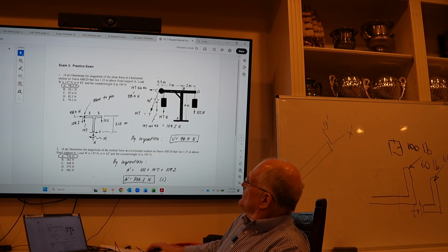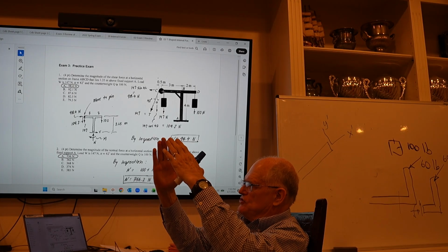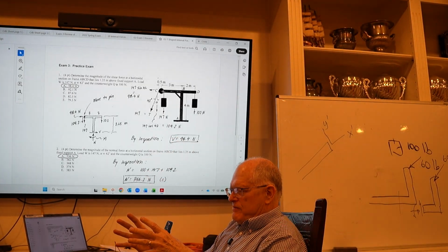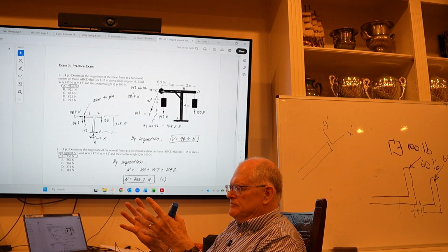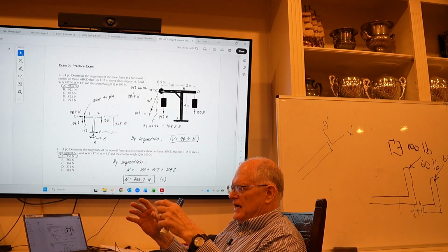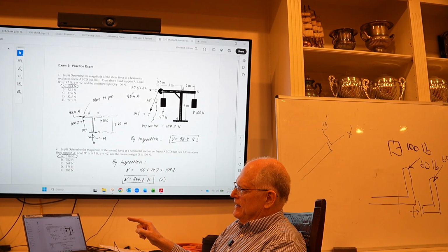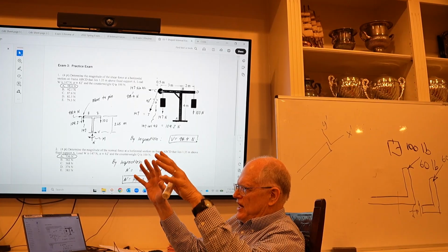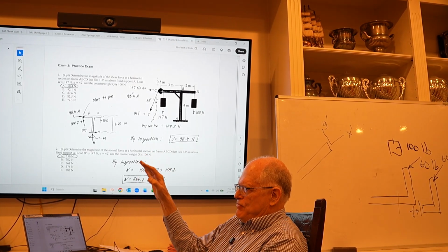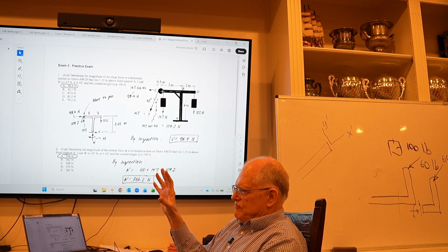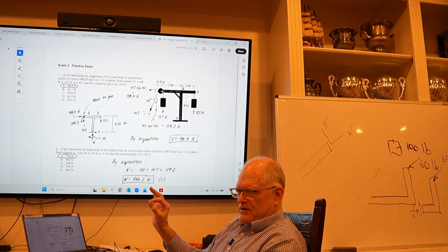So we can take this, these are coming off of 2 sides of a pulley. I don't know if you remember, when you draw the free body diagram of a frame, and there's a cable coming off the frame around a pulley and then back away, in the process of cutting the free body diagram, you cut both of those cables, and you can concentrate them at the pin.